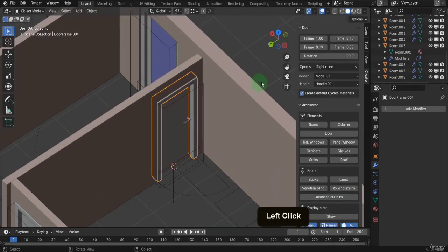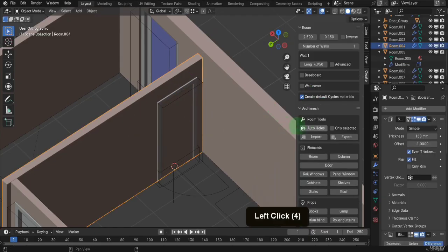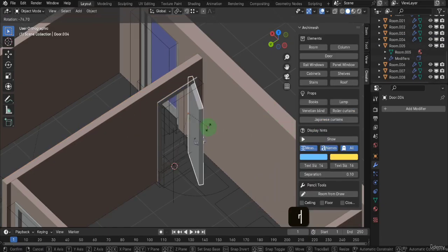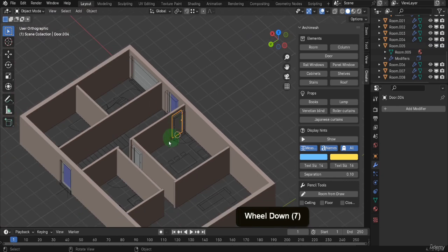Select the door frame. Now change the direction to open left. We need to update the subtraction again. That will be the process for the remaining doors. Make duplicates and position at the 4 remaining doors on the ground floor. The garage door is slightly wider, so that will need to be increased in width. I can do that between videos, so try get that done before the next video.